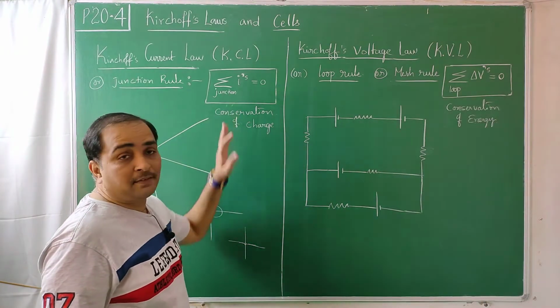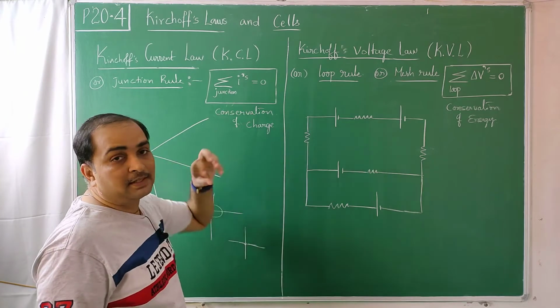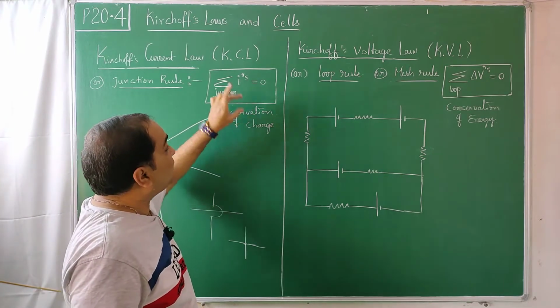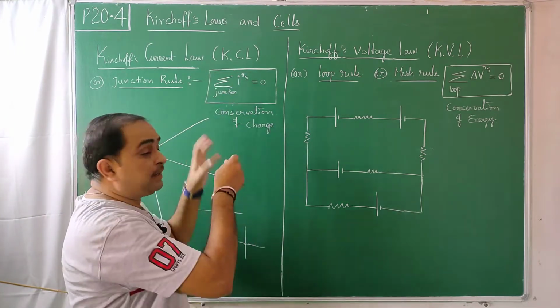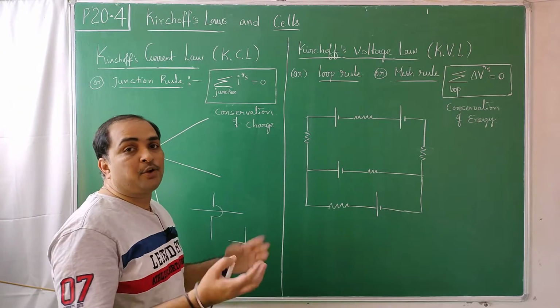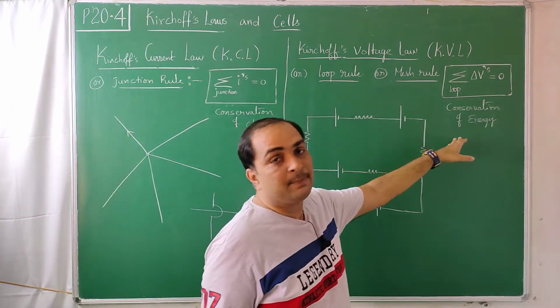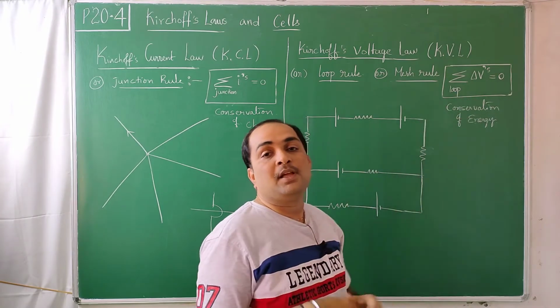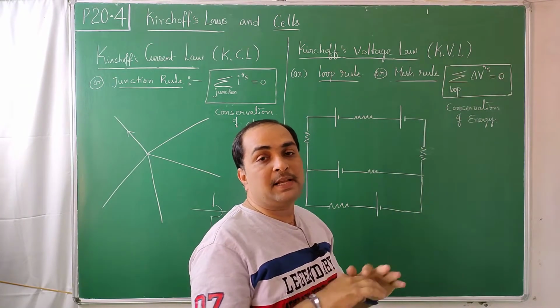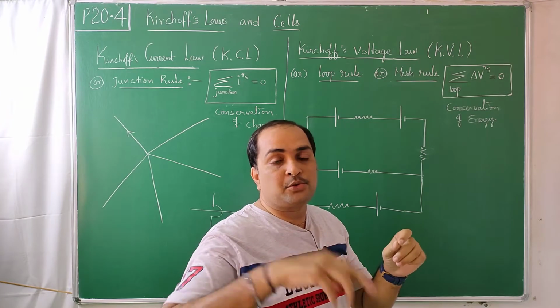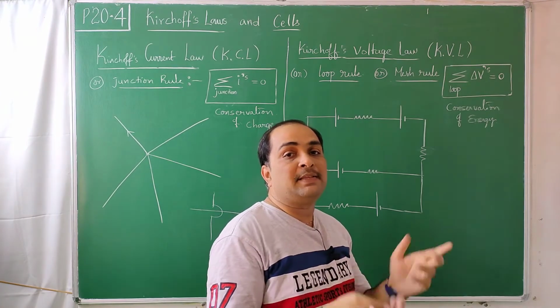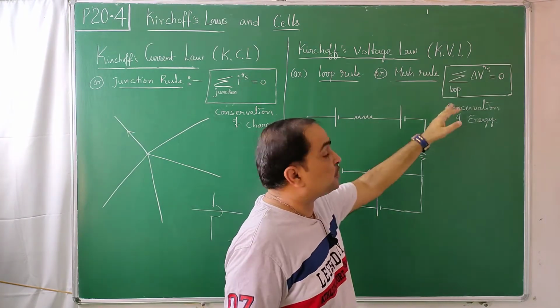Even though this is basically conservation of charge, it should not be looked at as just charge. Here currents are involved, so he applied it to a particular case of circuits where current is coming and going. Here also it's not just energy, it's potential differences. In a circuit, he took one point, traversed different places and came back to the same place. Then energy is conserved, that he wanted to say.